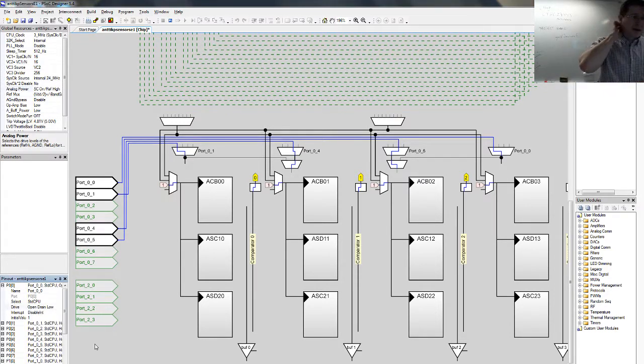So those are the input drives. Okay, then any of the pins can be used as an interrupt source. Any pin will generate one single interrupt, meaning that in the interrupt service routine, if you have more than one pin interrupting, you need to check which pin was the active one. But anyways, it's quite universal.